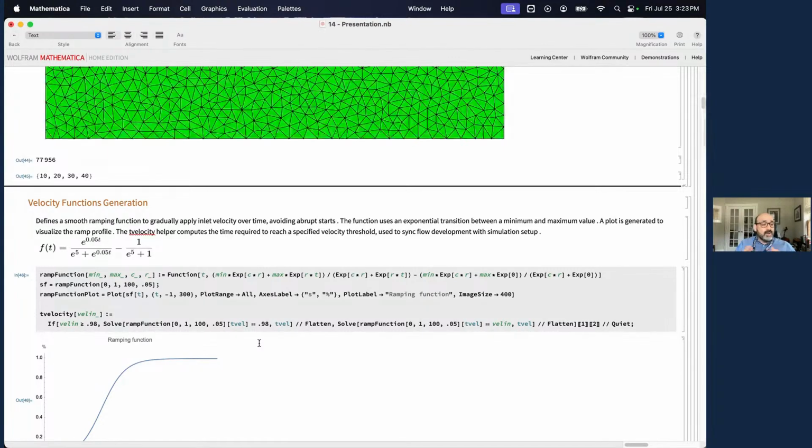So I was able to solve the Navier-Stokes equation up to a certain velocity, in this case 1 meter per second, but the actual data came at 10 meters per second. If you solve the Navier-Stokes equation at 10 meters per second, it will not solve, because of all the turbulence that I'm talking about. So I got down to a solution at 1, but how do I get the results to 10? I used linear interpolation to get an approximate solution to the Navier-Stokes equation.